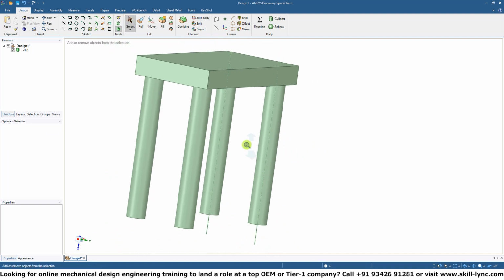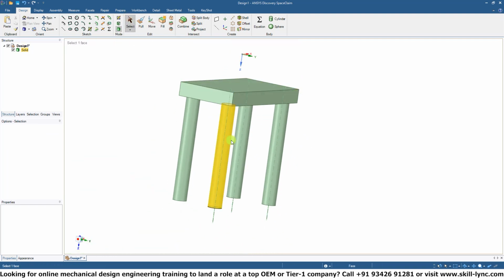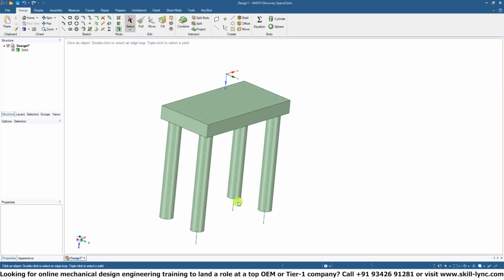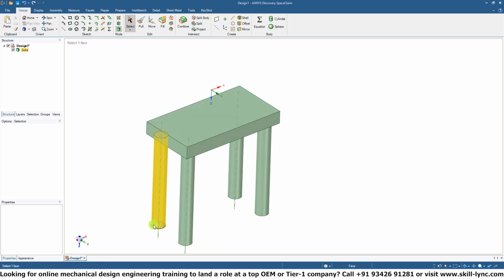Let's imagine that you want to build this along the Z direction with the feet being at the base on the build plate. So what would happen obviously is the only contact area that you have with the build plate is the combined surface area on the bottom of the legs or on the feet. Considering this, you'd only start off on the first layer just with a few circles over here and here. And as you start going up and building this area, you'd have a really long cylinder with a very narrow area in contact with the build plate.